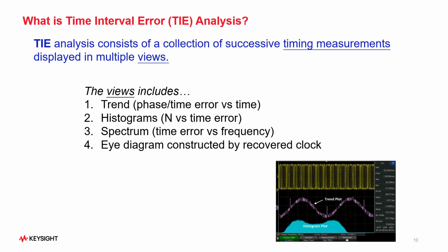During the course of the presentation, we'll spend much more time discussing how the TIE trend waveform can be interpreted relative to the NRZ data signals for specific components of jitter. Other useful views of plotting the real-time measurement results that can provide additional insight into the source of jitter include histograms, spectrum displays, bathtub curves, etc.